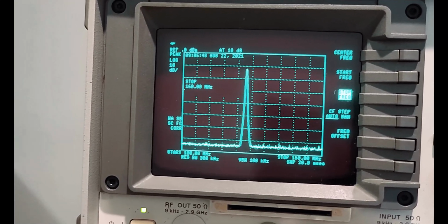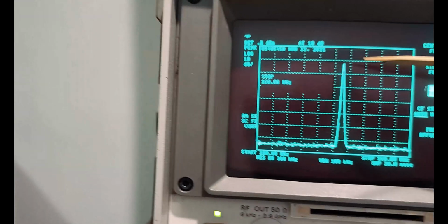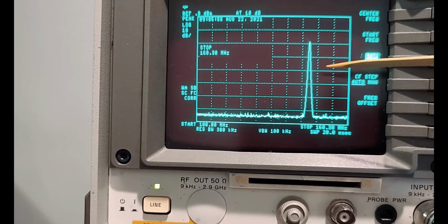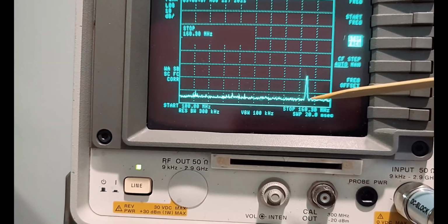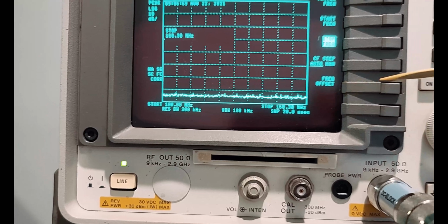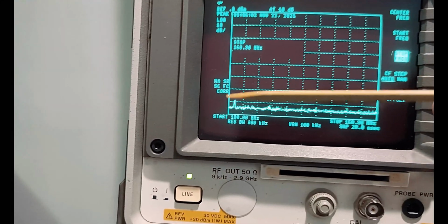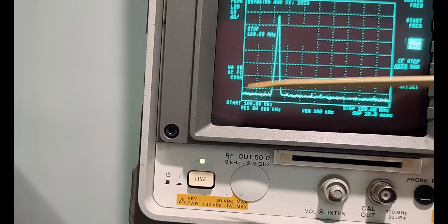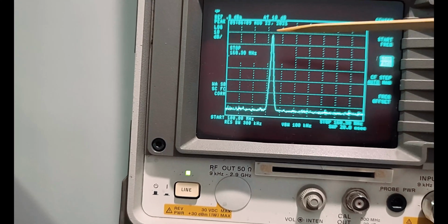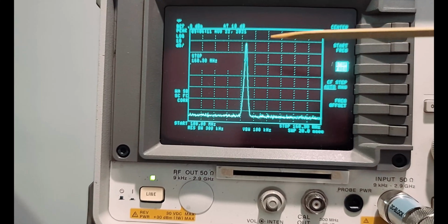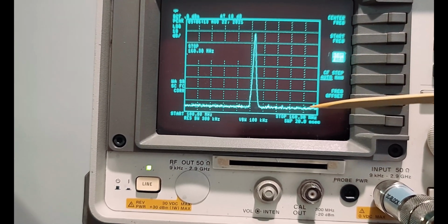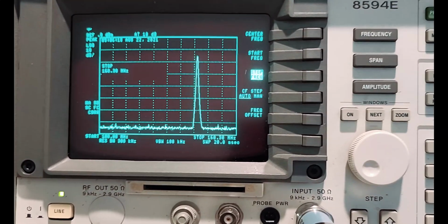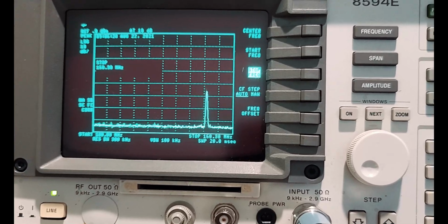Now, right now, what you're watching here is the peak, and it gradually dips because the filter is going to reject beyond that 136 megahertz. And on the far left, it's going to pick up again because that was a reject side of the filter behavior. Now it's picking up as a pass through, and then it's going to dip again once it gets to the other end. All right, so that's good.